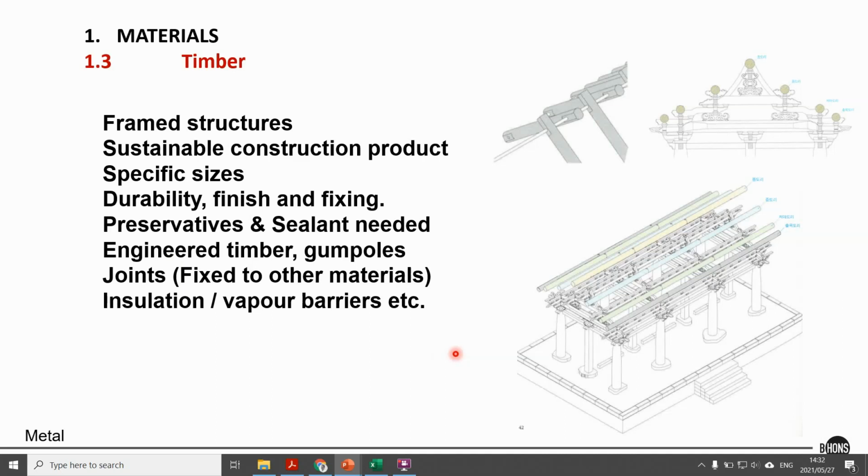But you must use insulation, and once you use alternative insulation, remember to use vapor barriers. That's on the outer layer of a wall, and between the outer timber paneling, that's the waterproofing, to use something that's a wind barrier, and then also prevents any vapor from building up in the insulation, because that damages the insulation in the process.